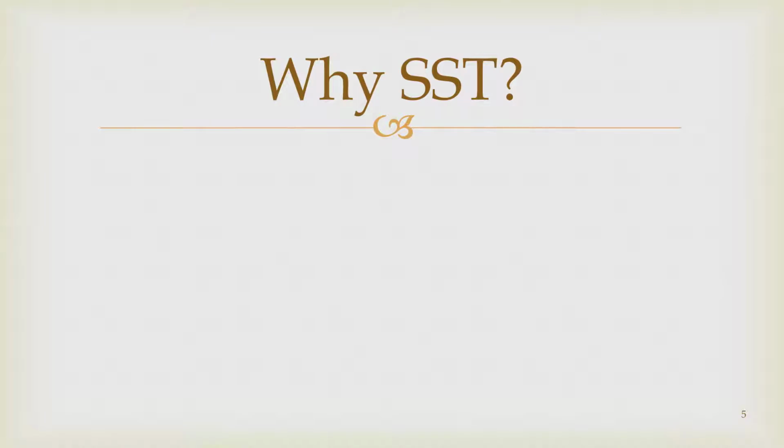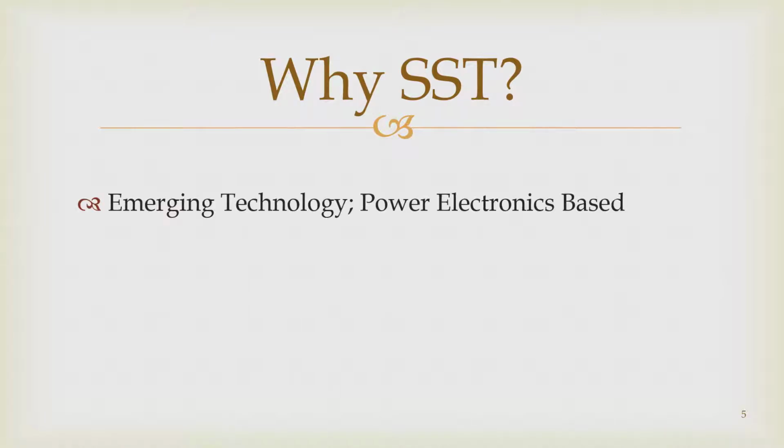Now, why solid-state transformer? First of all, the use of power electronics converters-based transformer is a very attractive technology because of the quick advance in power electronics nowadays and the emergence of silicon carbide switches that have high capabilities in terms of voltage levels, in terms of switching frequency, better than its previous alternatives.